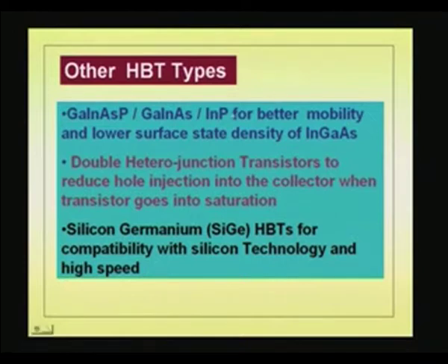benefit. One is gallium indium arsenide, as you know, has much better mobility than gallium arsenide, okay? Because indium arsenide has got higher mobility. When you mix with gallium, gallium indium arsenide has got better mobility, but in between indium arsenide and gallium arsenide. The band gap also is different from that, lower than that of gallium arsenide. Okay. Now, but you get fairly decent band gap there, but main reason is it gives better mobility. So, on the top of that, of course, you put this material which has got a wider band gap region.